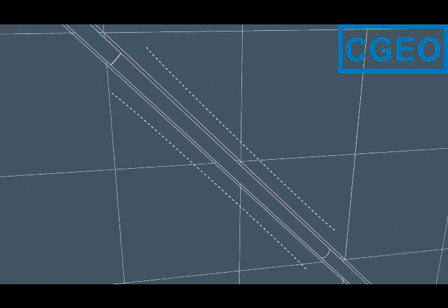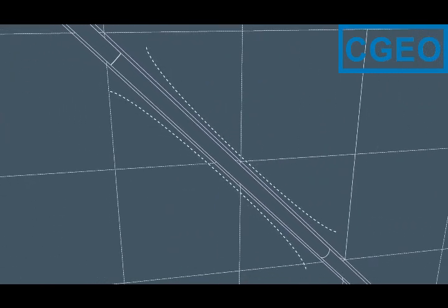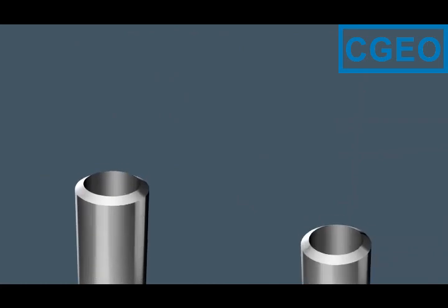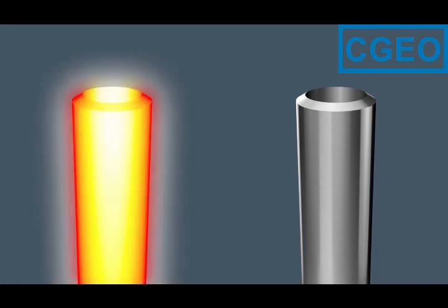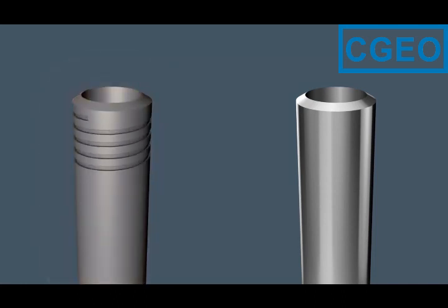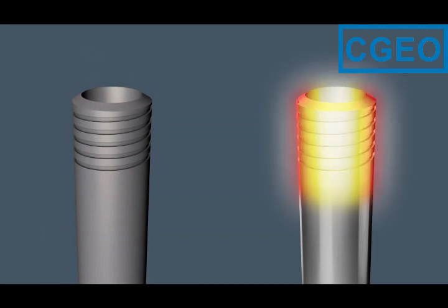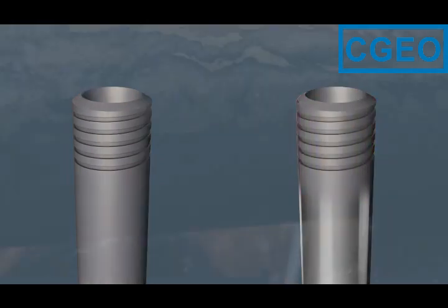In deep hole drilling, the weight of the drill string increases the requirements on the drill rig torque and lifting force. To maximize the depth capacity of the core drilling machine, special drill rods are designed with a thinner body to decrease the weight of the drill string. Wireline drill rods are made out of a seamless blank of high-quality steel. Either the blank is heat treated before turning the threads, or the blank is threaded first and then the threads are heat treated.